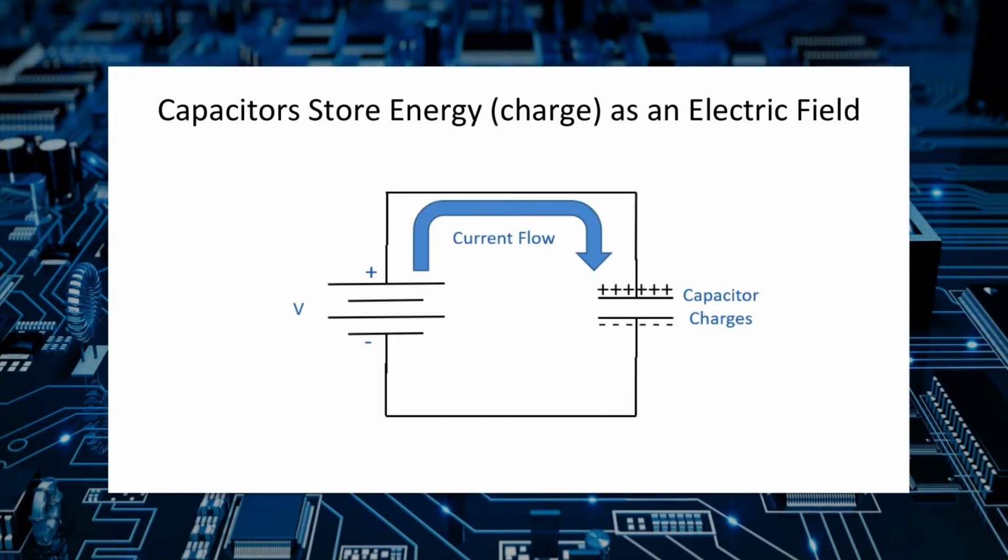You'll recall from our last lesson that when a voltage is applied across a capacitor, current flows and the capacitor charges. Once the capacitor is fully charged, current stops flowing. While the capacitor is charging, the voltage across the capacitor is changing. The current through the capacitor is also changing. To be more specific, the voltage across the capacitor is increasing, and the current through the capacitor is decreasing. During the time these changes are taking place, the capacitor is in a transient state. Its response is changing from one condition to another.